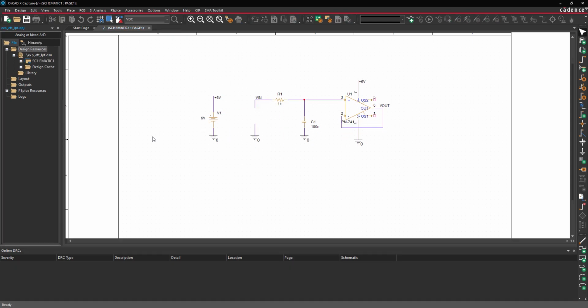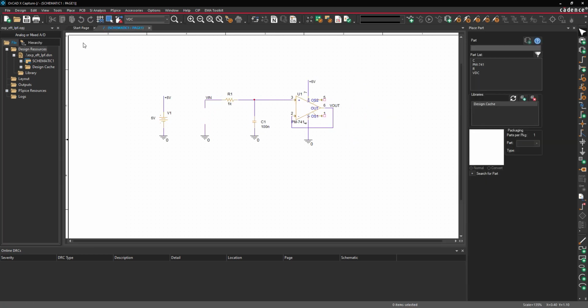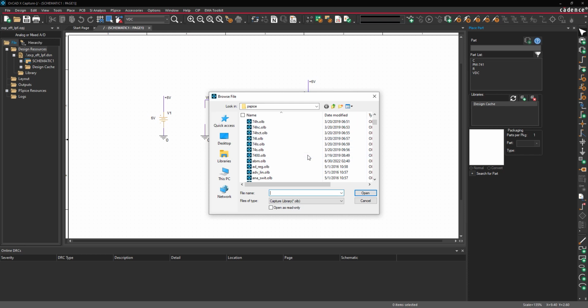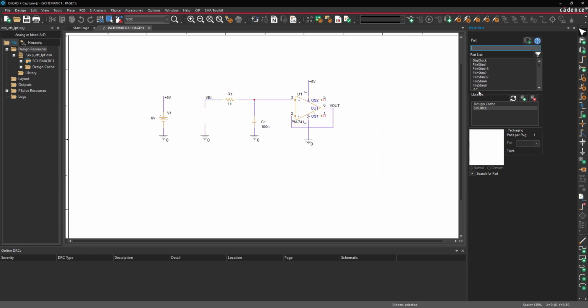If you are running PSpice 23.1, the burst exponential source is not listed in the Component Explorer. Select Place Part from the menu. Select Add Library under Libraries. Select the source library and click Open to open the parts list. Select VEXPB and click Place Part. Click to place the part in the empty space, then right-click and select End Mode.